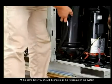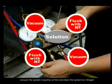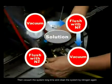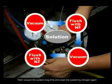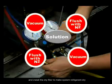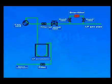At the same time, you should discharge all the refrigerant in the system. Vacuum the system long time at first and clean the system by nitrogen. Then vacuum the system long time and clean the system by nitrogen again. Repeat above process several times. You can change all the refrigerant oil if necessary and install the dry filter to make system refrigerant dry.